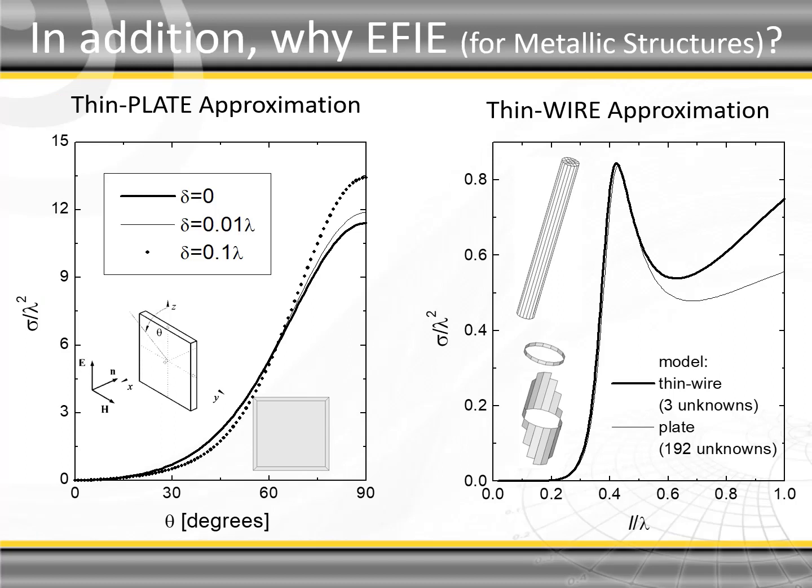In addition, EFIE is the only surface integral equation that enables thin plate and thin wire approximation. In the first case, shown left, the plate of thin thickness can be replaced by an infinitesimally thin plate if its thickness is much smaller than the wavelength. In that way, the number of unknowns needed for EM modeling is halved.